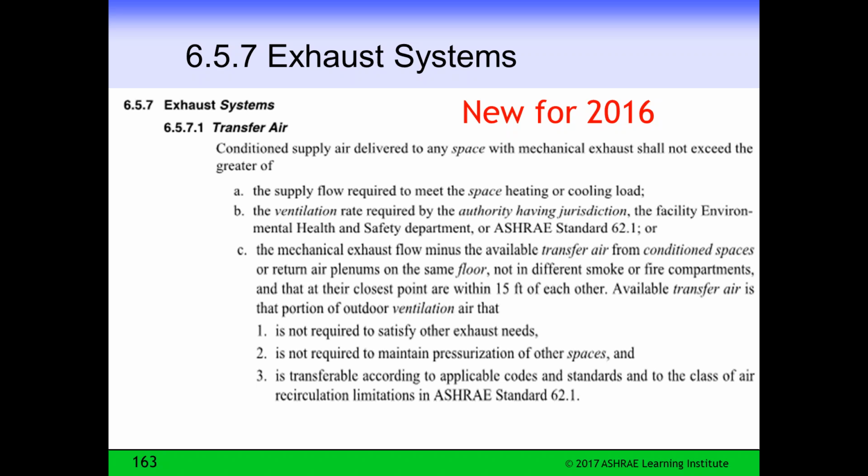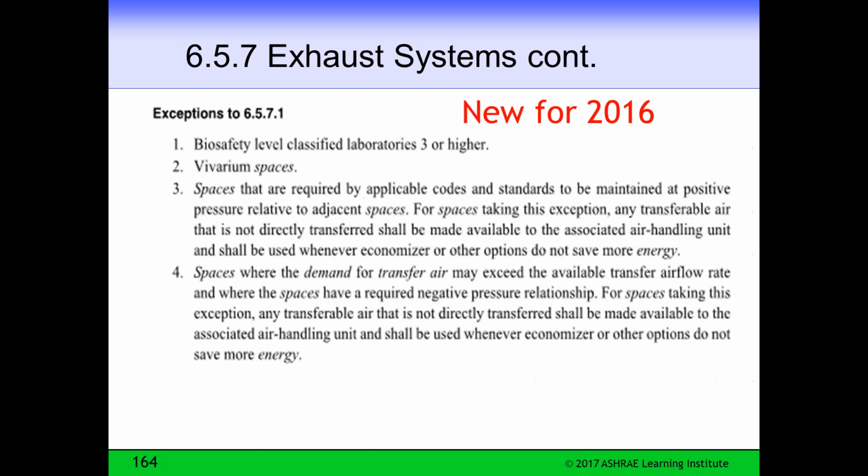So what this is asking you to do is to make sure before you put extra air into a space that's just been heated or cooled just to be thrown out through an exhaust fan, that you've explored these other ways to make up that fan and still cool the room or heat the room or keep it comfortable. And transfer air is an especially good idea in those cases. So these are the exceptions to that requirement.